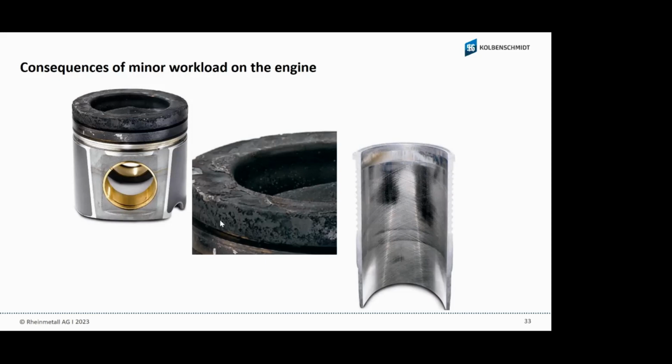I have one question. Why is there carbon on there? Why is there carbon on the top of the piston, or when does it build up? Collection of oil and fuel that's been burnt? Not the fuel, the oil is burned. When oil comes up past the piston rings and into the combustion side, then the fuel is burning, and then it burns also the oil. And when oil is burned, then we have built up carbon.